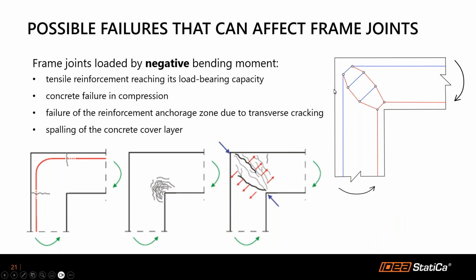Or you can introduce a more sophisticated strut-and-tie model where you create this bottle-shaped strut, which is made of these struts that you can see here, and in between them there are ties forming, and this way you can get the exact forces that are in these ties and design the reinforcement based on that.